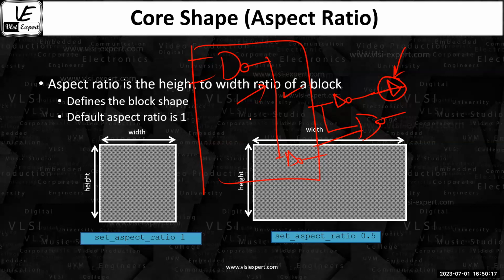Or maybe the delay is less. Based on that, maybe you have to further change this particular NAND gate. So right now, this NAND gate may be using an area of A1. Maybe later on, you have to change it to A1 plus delta A1, or maybe some A2 from the standard cell library.